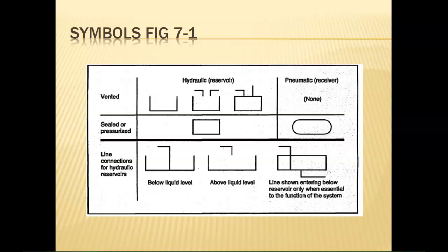However, if I set it above that line, I start trying to set it up here, what's going to happen when I start pulling too much fluid into my system? I'm going to run my pump dry, right? You're going to have a burned out pump, which is extremely expensive. So the reason you have to be aware of where that pump sits is because if it collects a lot of sediment, you're going to tear up your system because it's going to gunk everything up.